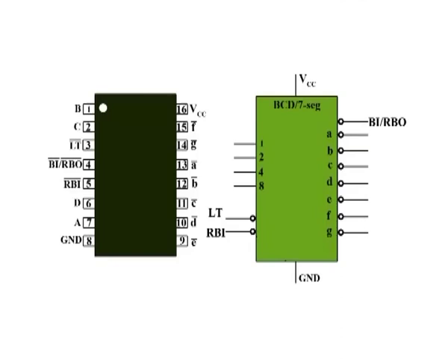In addition to decoding a BCD input and producing the appropriate 7 segment outputs, the 74LS47 has lamp test and zero suppression capability. When a low is applied to the LT input and the BI/RBO is high, all of the 7 segments in the display are turned on. Lamp test is used to verify that no segments are burnt out.